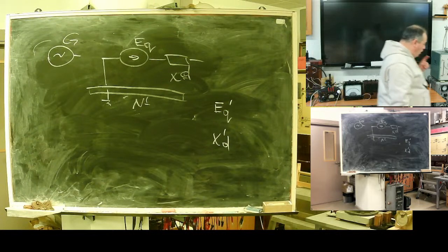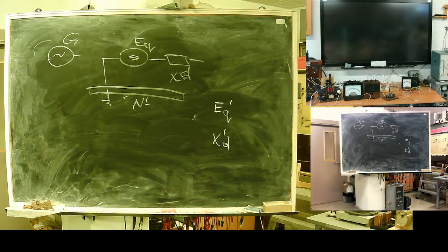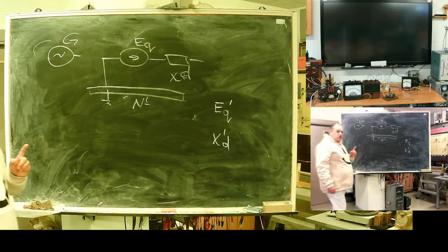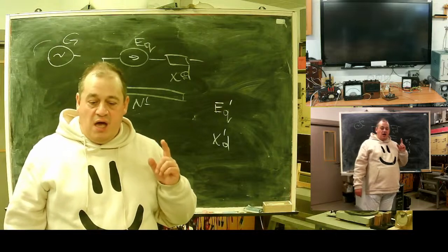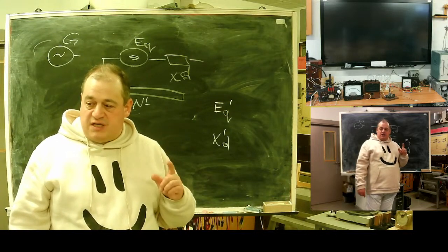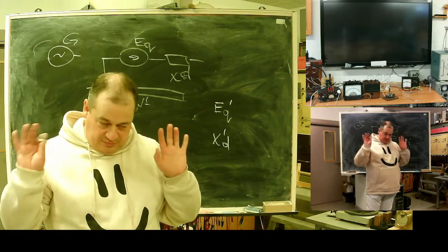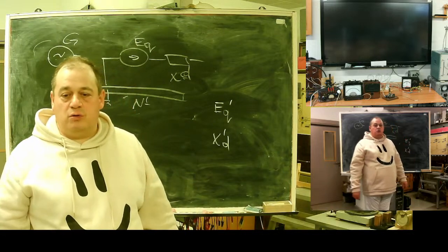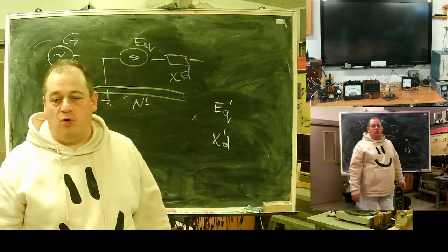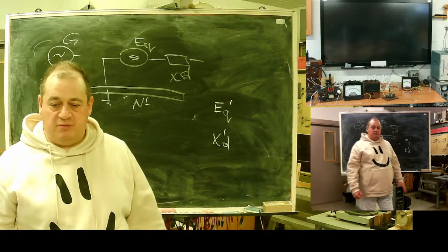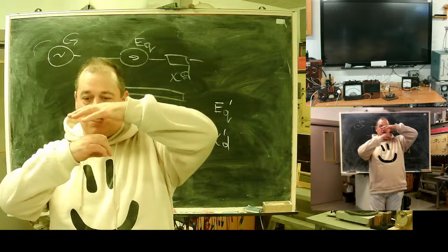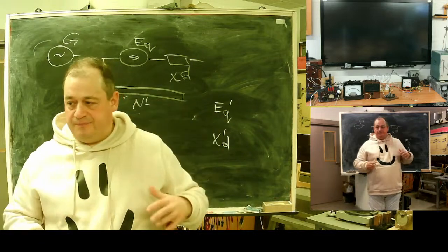There is one, how to say, maybe disadvantage or possible problem with synchronous machines. A simple synchronous machine without special means does not have, or has very small, asynchronous torque. This means that inside the pole division the rotor can oscillate.